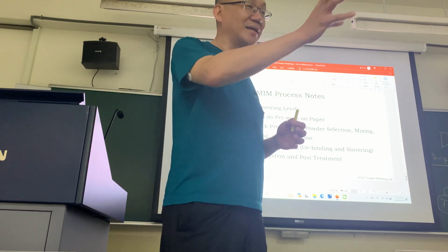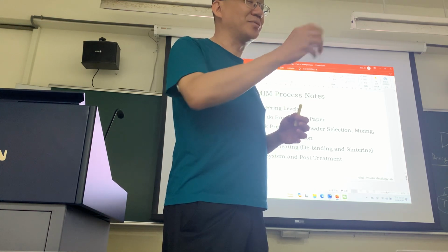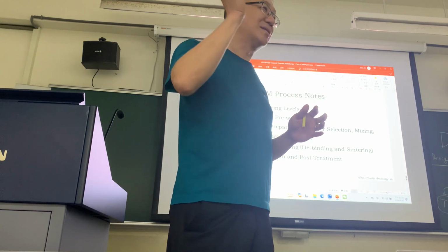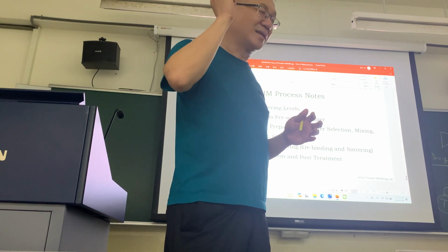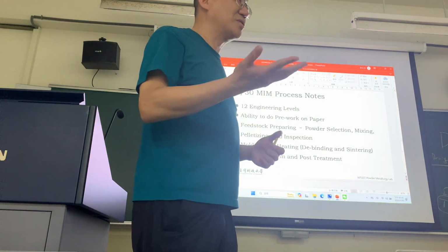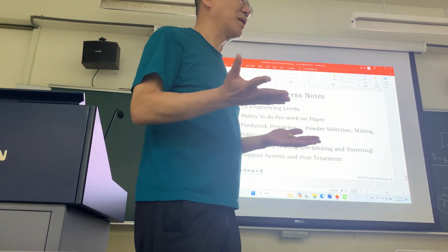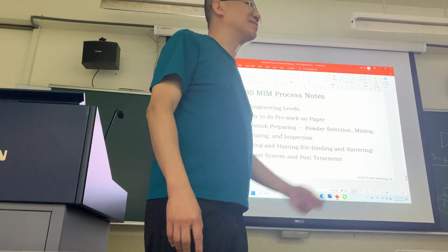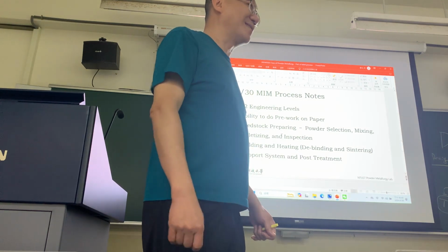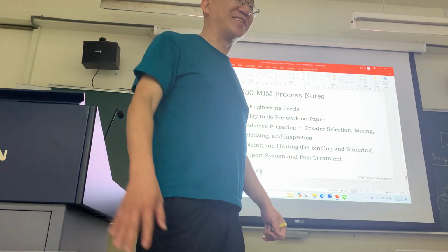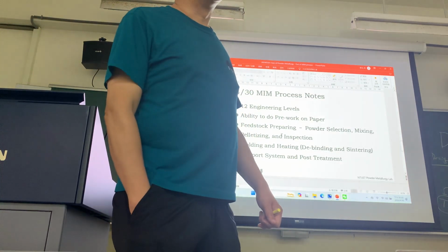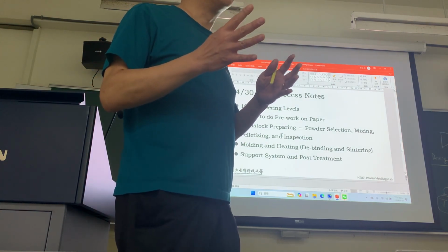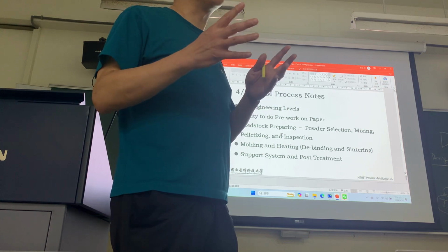So maybe everybody can discuss and we design a part like the NTU logo, make one model, then make a mold, make the MIM parts, make the feedstock, choose 316L or 17-4 PH material, then injection molding, debinding, and sintering. I hope everybody can join, but it's a difficult job. The first time you think, oh, this is very dirty. Yes, right, because everything should be good.